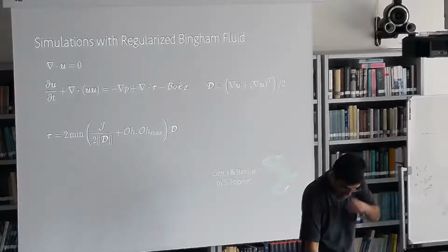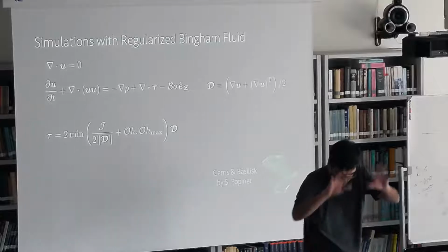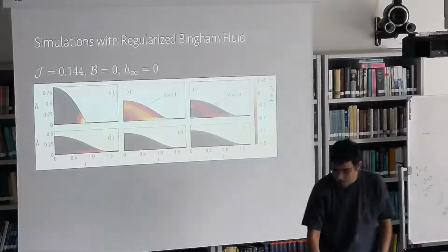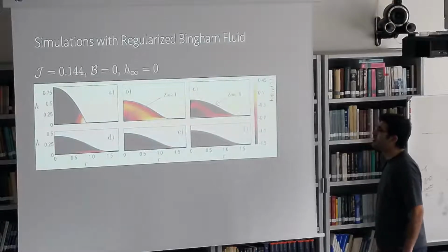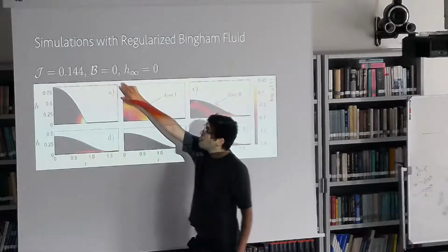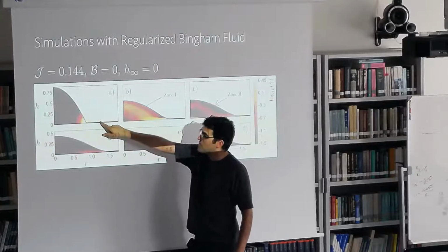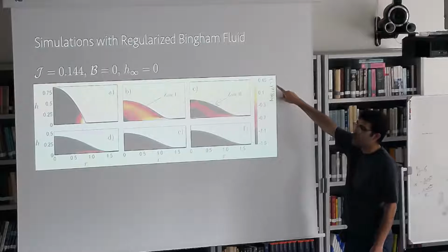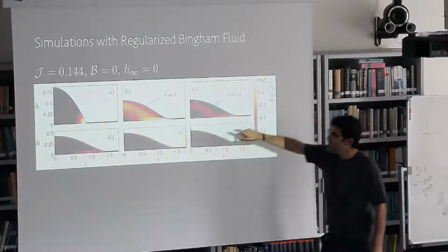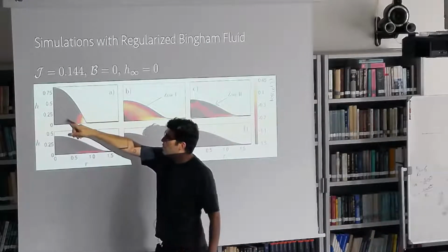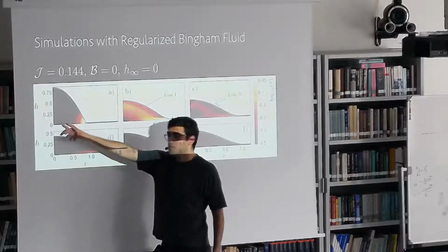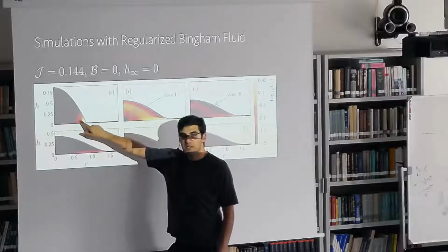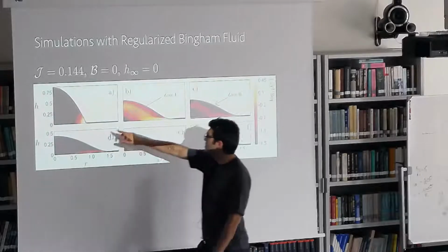So we solved this with Gerris or Basilisk, for instance, like the bubble collapse that I showed you in the beginning. And here are the solutions. So this is a droplet. Again, no gravity. The color that I'm showing is the log 10 of the deformation rate, meaning that if it's black or dark, there's not much deformation, and if it is white, this is a lot of deformation. So here curvature is maximized, so you get a lot of deformation, and it starts spreading.